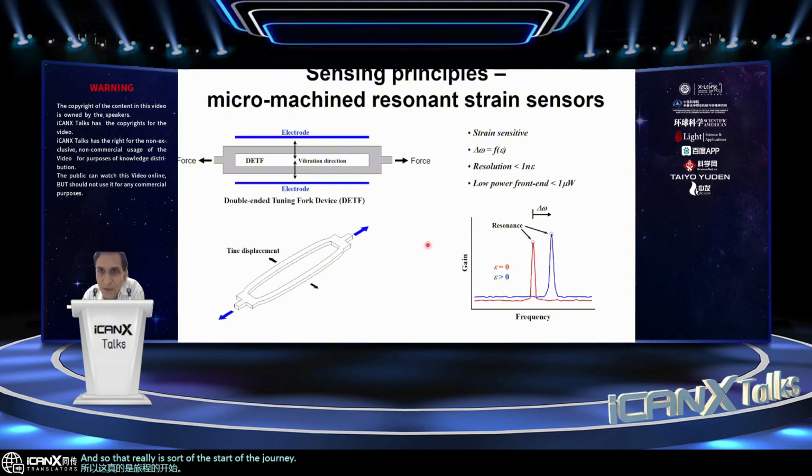And at Cambridge, I initiated a number of projects that followed on. I had a particularly good collaborative partnership with a civil engineer at Cambridge, Kenichi Soga, who's now moved to UC Berkeley. And civil geotechnical engineers were interested in strain measurements in structures such as tunnels, bridges, and other areas where, in fact, conventional vibrating wire gauges were used. And we kicked off a series of projects looking at MEMS-based strain gauges. And this was in the 2000s or so.